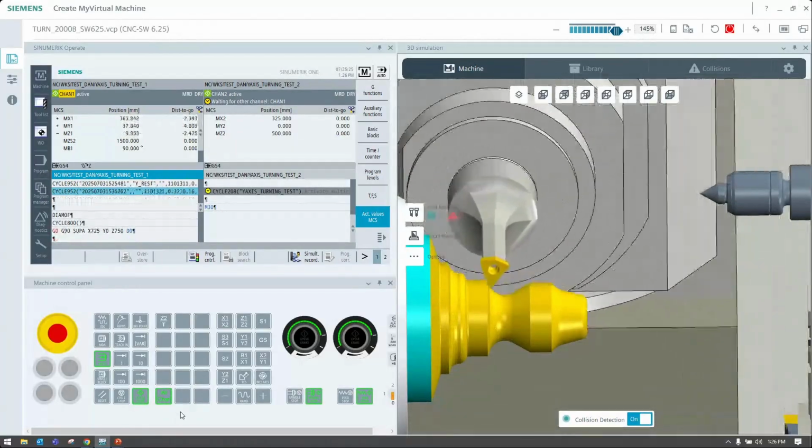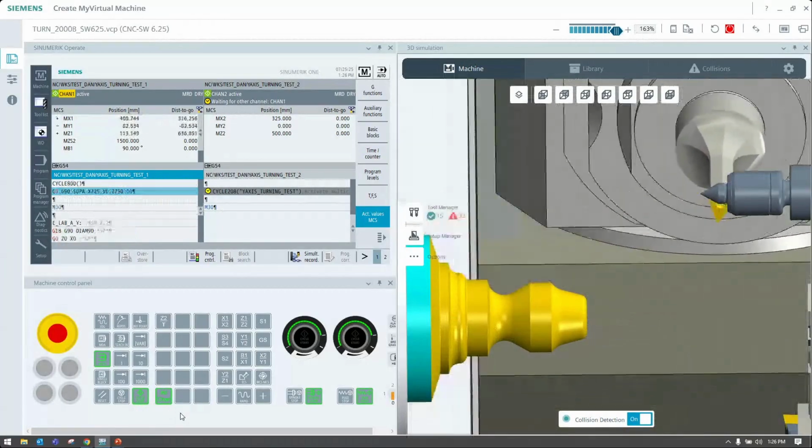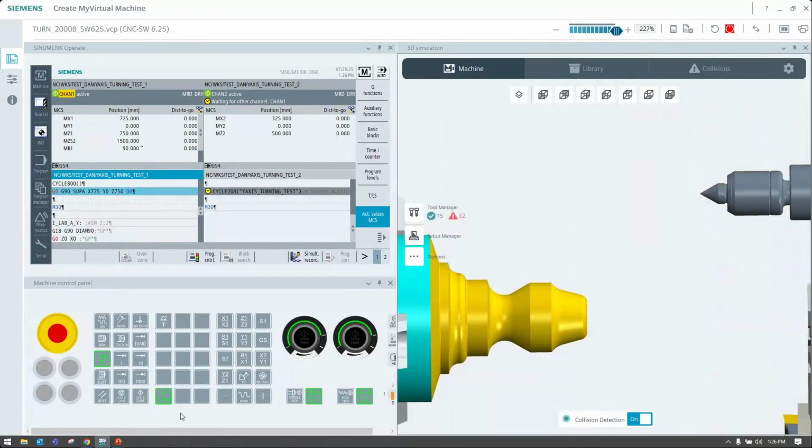I'm sorry, you were in the middle of speaking, but I do have a question for you. Obviously what we're showcasing here is on B-axis technology. Is there any benefit to Y-axis turning on a turret style machine? I think there would be some benefit. I think a lot of benefit would be in the Y-axis cutoff. I think that is huge on a traditional 2-axis or 3-axis turning, because you definitely can see that benefit there.